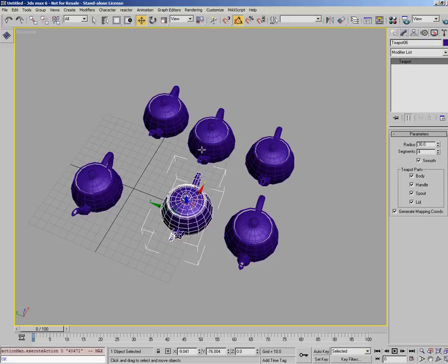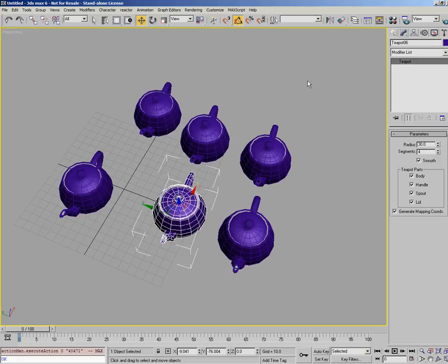Okay, let's move on to some of the other elements that we have in 3D Studio. I'm just going to hide this toolbar here. There we go. Right then, at the bottom of the screen you can see the timeline. You've got the timeline scrubber here. You can move that up and down to actually move backwards and forwards in time. On there you can see it tells you what the current range is. You've got 0 of 100, showing that you've got 0 to 100 frames there. This little blue bar here indicates exactly what frame you're on currently in time.